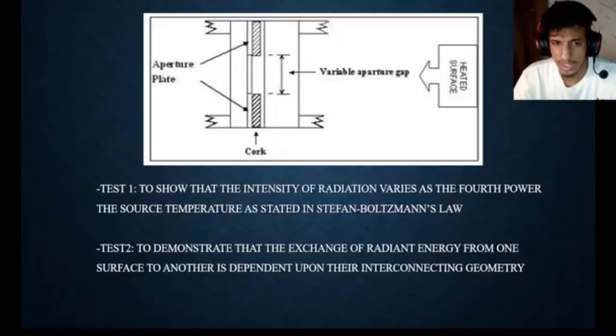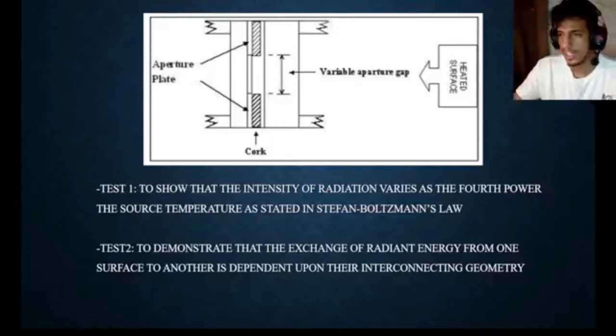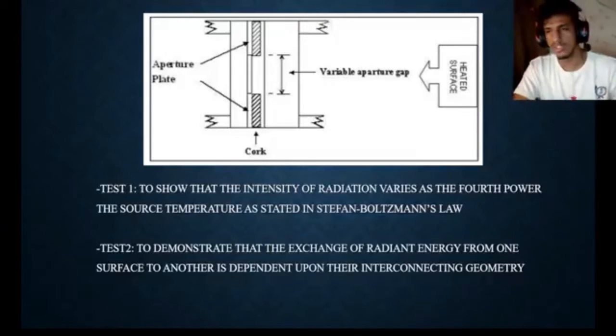When the T4 value has stabilized, move the radiometer position to 100 millimeter from the aperture position. Next, install the aperture plate on the aperture holder, adjust the width to 5 millimeter and calculate the area factor. Lastly, plot the area factor against aperture width graph. And that's for me, and my friend will continue with the result and calculation.